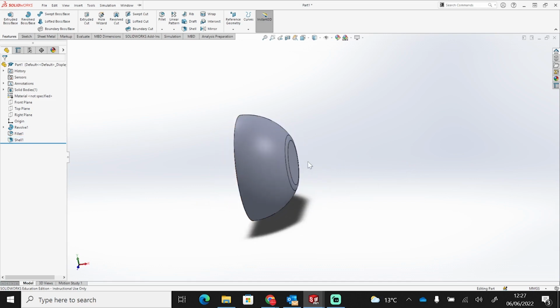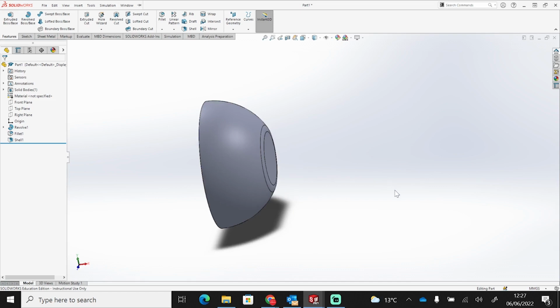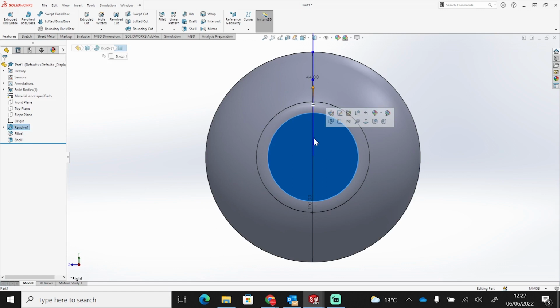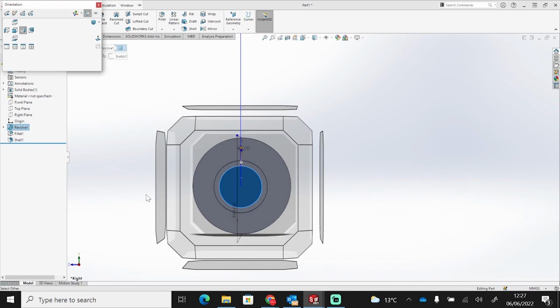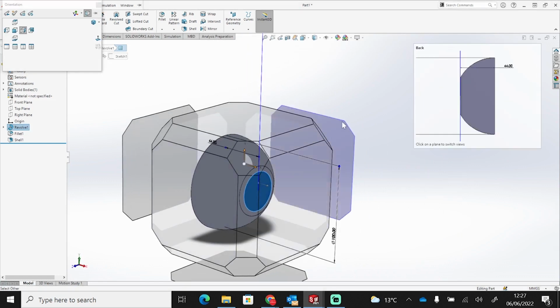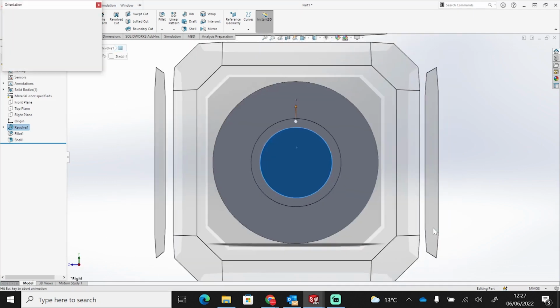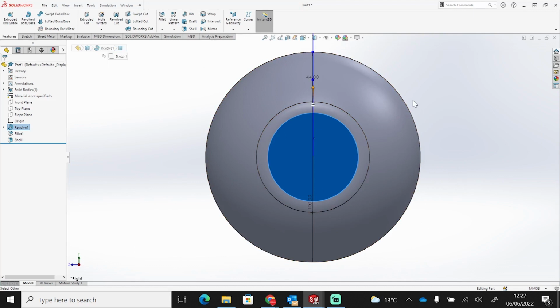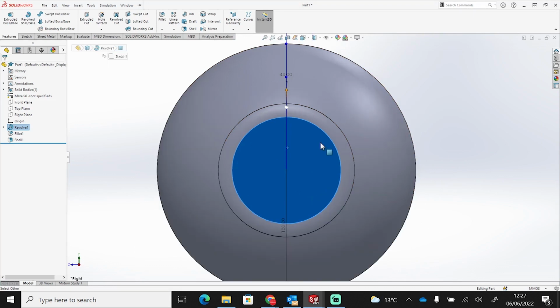Then all I need to do on the back of here is add in my holes to speak through. So I'm going to click that back section there. I'm going to click this back circle. Now for that quick feature you just saw there, to be able to orientate your model quickly, if you hit the space bar, you should get the option to use that orientation feature. And then we can move to which orientation we want.